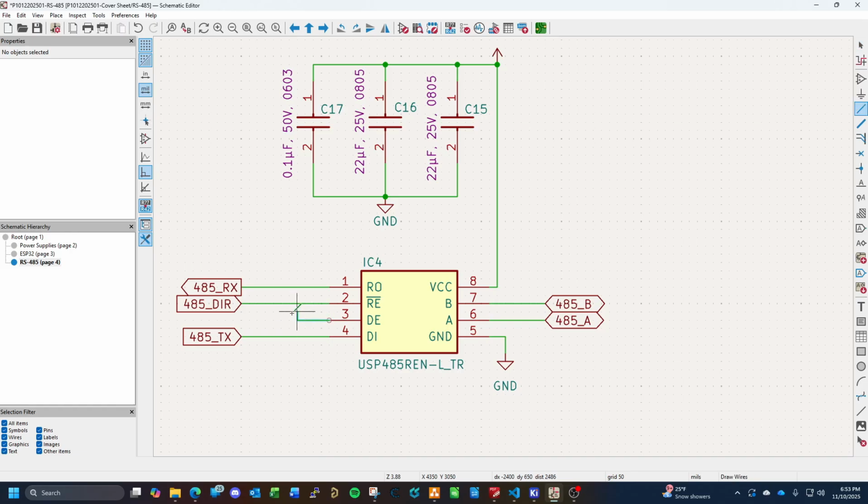These guys, because of the way it works, you pop those two together because based off of the output mode of that DIR pin, it's either going to be in transmit mode or receive mode. Typically, you want to keep the UART chip on a peripheral device like this in receive mode, so it just waits for input, and the central system, the microcontroller, basically handles all the flow.